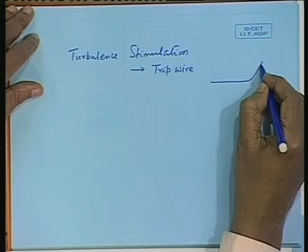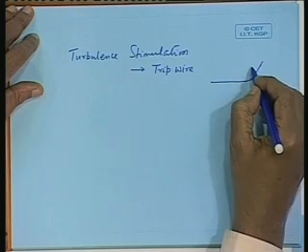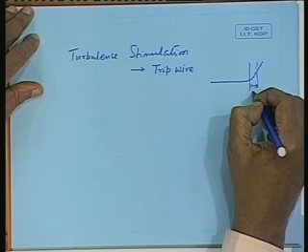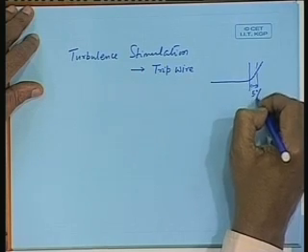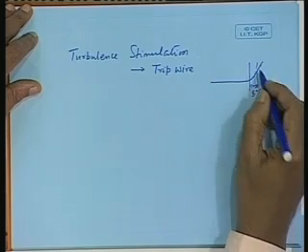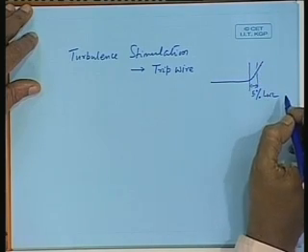And what we use is called a tripwire. This is the normal turbulence stimulator used in ships. That is, I have a ship model here. I can put a wire right on the front of the ship, about 5% of the length aft of FP, LWL, length on water line. Normally in model tests we use length on water line.